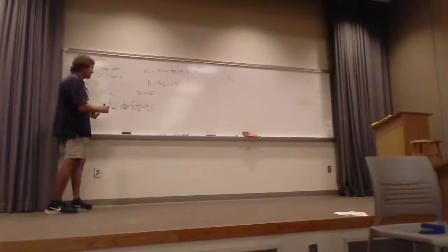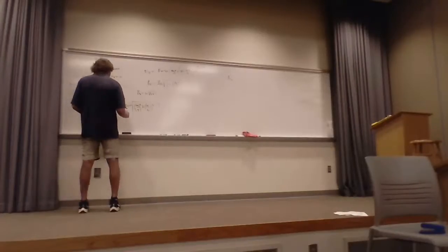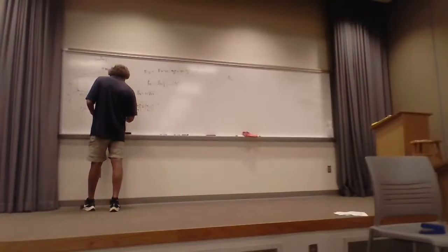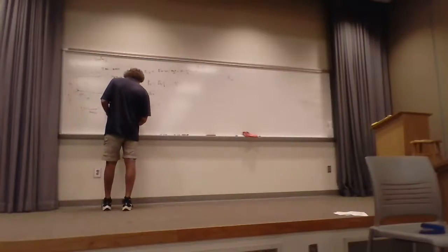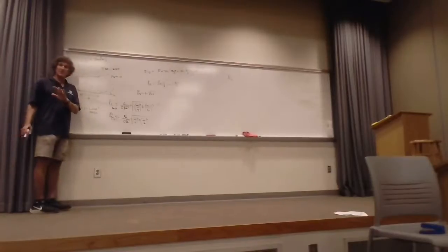Now, that gives you the lowest order of the frequency. Therefore, the lowest TM mode that will propagate is when the frequency is for 1,1, and that would be C over 2 square root of epsilon relative, and then it would be the square root of 1 over A squared plus 1 over B squared. And that would be the lowest order frequency for the TM mode. Y'all hear me on that one?